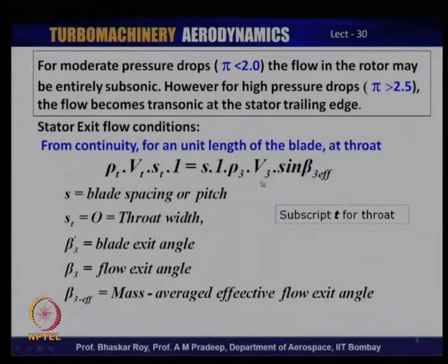Now, this allows us to start talking about the blade spacing or the pitch or the packing of the blade, which also of course, would tell us how many blades we would need to have. And of course, as we know, the spacing to chord ratio is an important parameter in blade design of turbines and indeed that of compressors, as we have seen before.